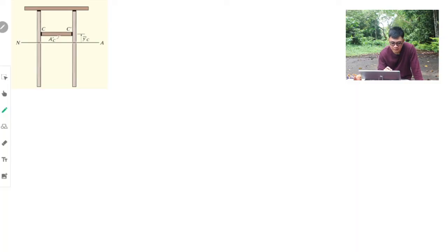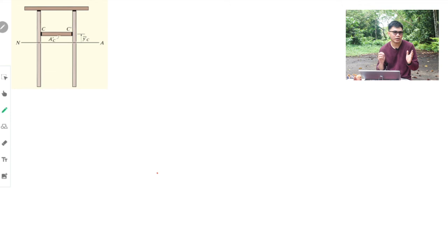Okay, so how about we have this beam? This beam asks for the shear flow at this portion here. We will just imagine this, we will not solve it, but what will happen to our solution? What will change in our solution? The same shear force is applied, which is the 850 kilonewtons. How about your Q? Will your capital Q be affected? Yes, of course, your Q will be affected because what area are we considering now? This is the area we will consider.